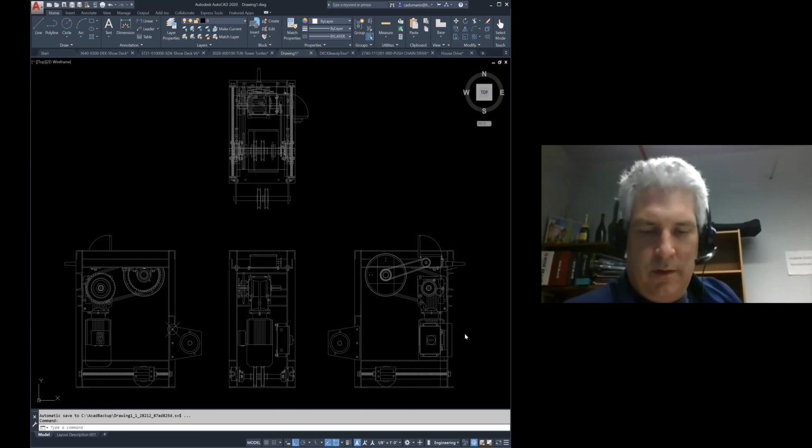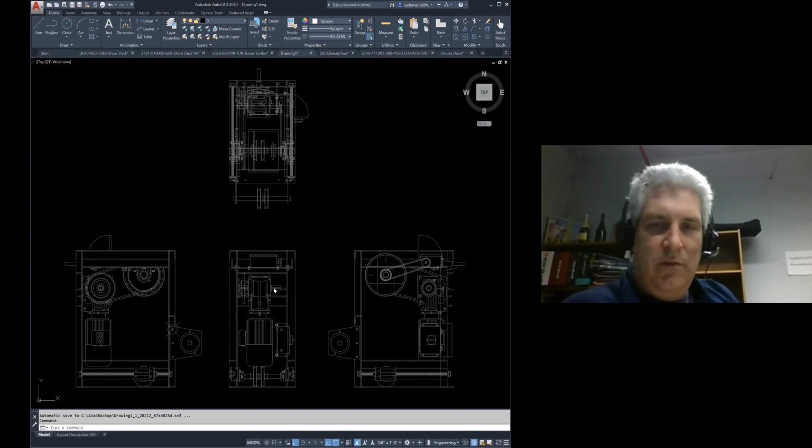Back probably when Loren started in the 80s and even continuing until I started at Hudson, DC motors were pretty prevalent, and that was mostly about speed control. I think we'll come back to that in a minute. But nowadays you see a lot of typical AC gear motor type stuff. There's usually some second stage, most often done with chain, but you sometimes see belt or other things to couple the output of that gear motor to the shaft that is actually turning the drum.